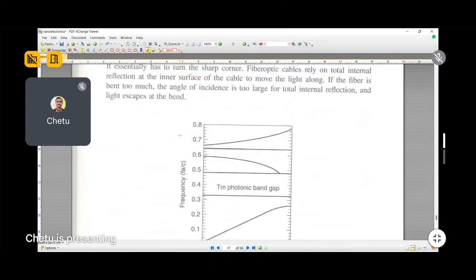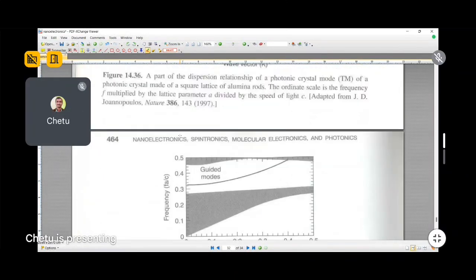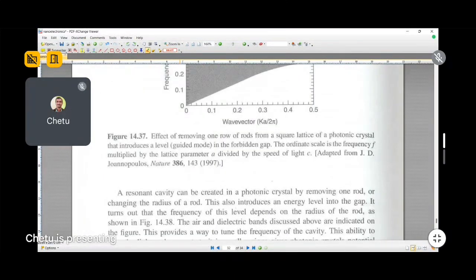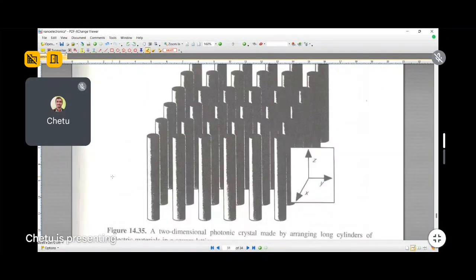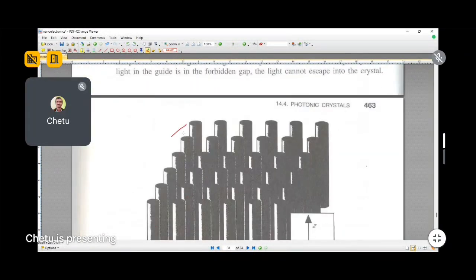And for the semiconducting material, you don't need to apply specific coating. Only if you make one side rough, like this part, this will act like a 100% reflecting mirror. So photon will come here in this direction and it will reflect back.